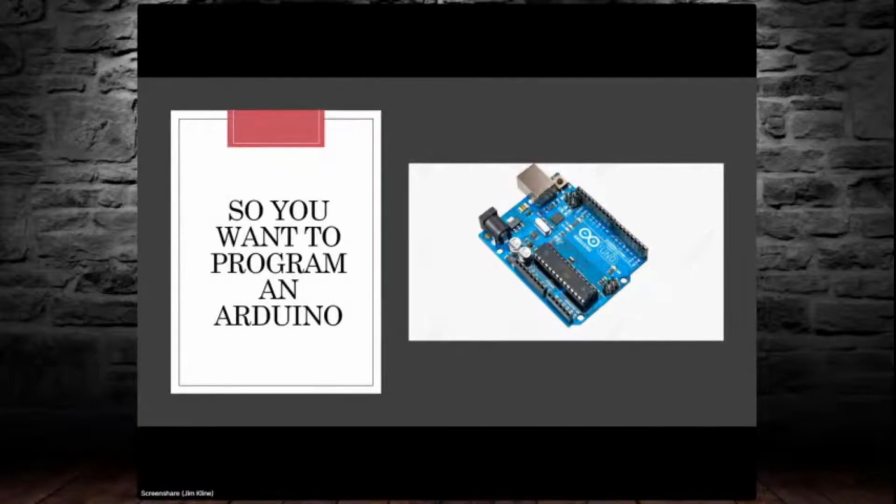One of the sketches is called Blink, which is a very basic sketch that will blink an onboard LED on the Arduino. A very handy sketch that will prove that your Arduino is operating and is able to accept the download. No wiring needed other than a USB cable that connects between your computer and the Arduino. I use the Blink sketch when I get a new board, much the same way you would check a new calculator by adding 2 plus 2 and checking the result for 4.